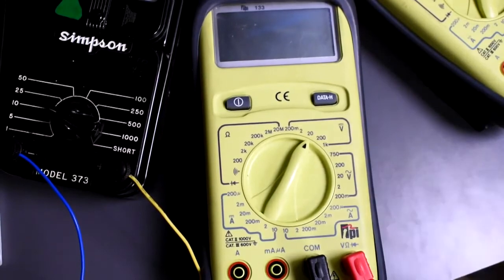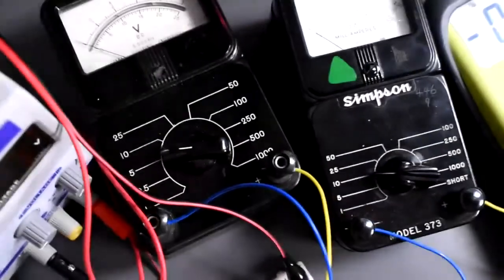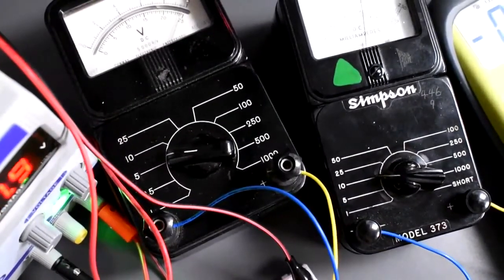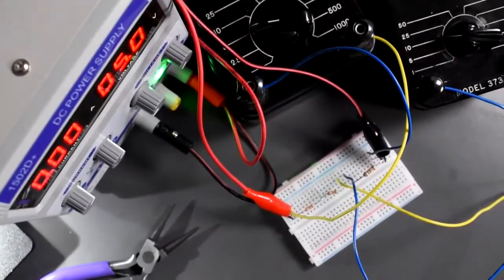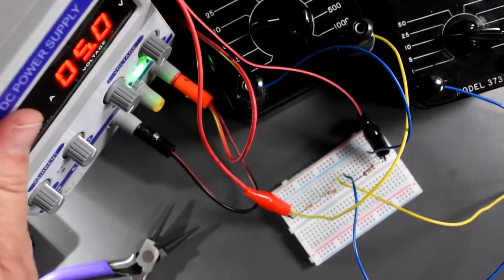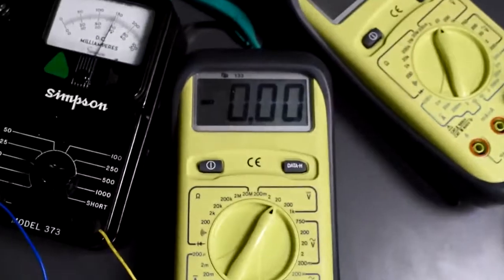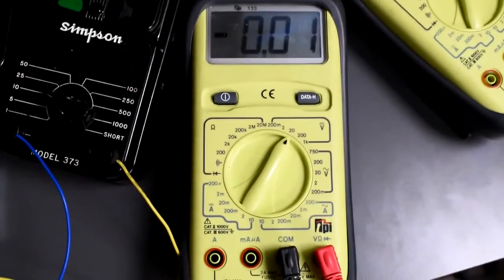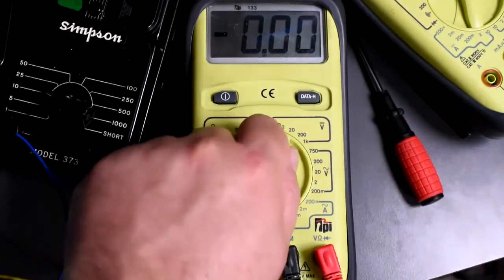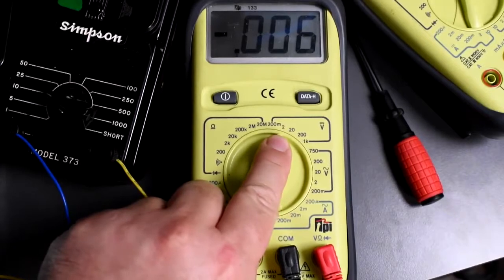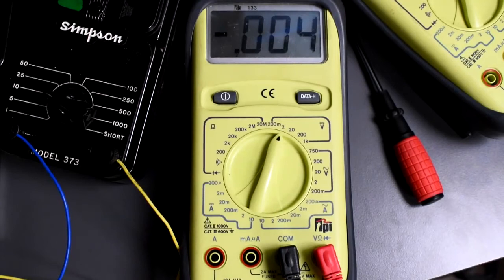Okay. Now, let's turn this thing on. What I'm going to do is set my power supply to 5 volts. Can you see that? Here's my power supply sitting at 5 volts. Okay. Now we're going to measure the voltage with this multimeter. Do we have a range that is 5 volts? No, what's still lower than 20? It's 2 volts. We cannot measure 5 volts when the range is selected to up to 2 volts because it's just going to show us.